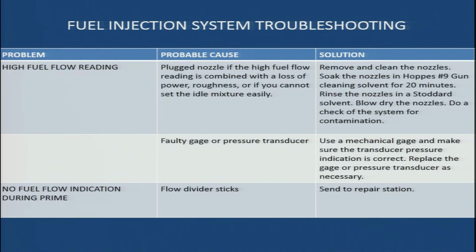In that case, we may face the problem of high fuel flow. If the nozzles are blocked, then we have to remove and clean the nozzles. The procedure is given here, and once the nozzles are removed and cleaned, there is a system to check the nozzles as per the manufacturer's guidelines.